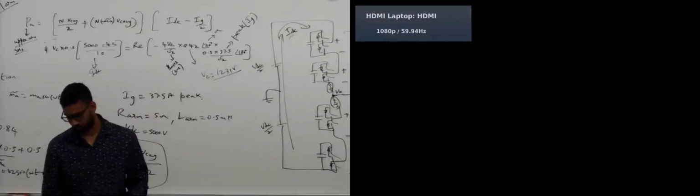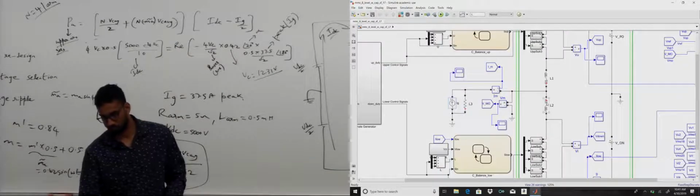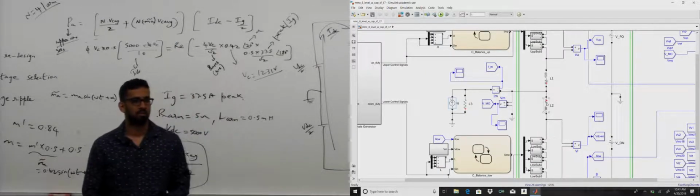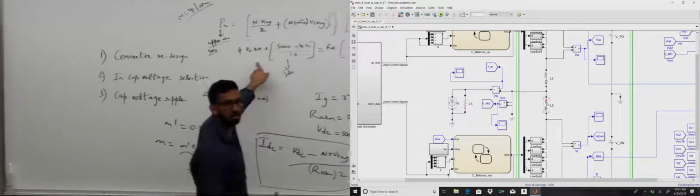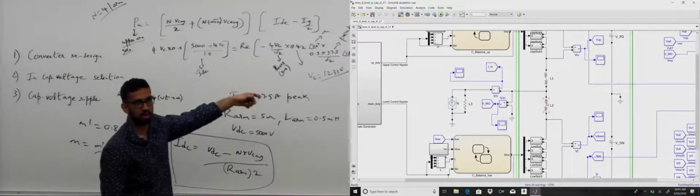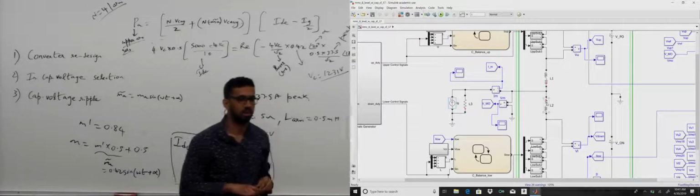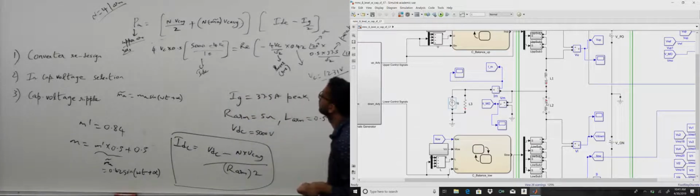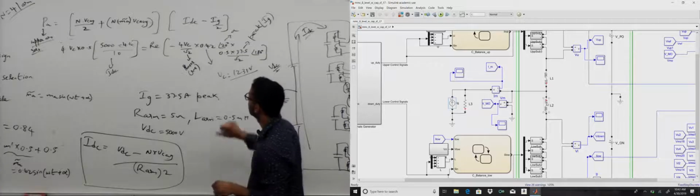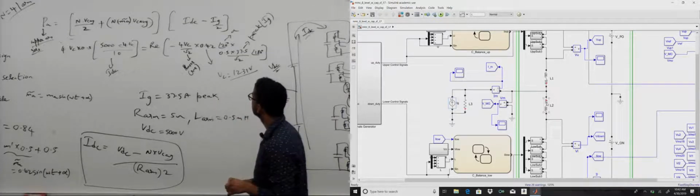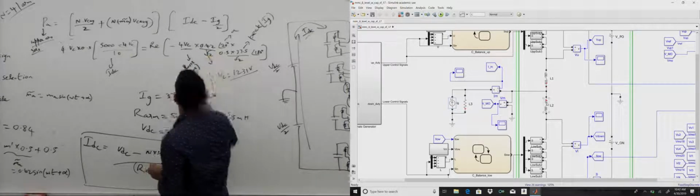Vishnu: For phasor representation, why is the one Vc average divided by root 2 and the other one is not divided by root 2? Here, this is not phasor. These are all DC quantities. Only AC quantities have phasor meaning, right? On the right side as well, n times Vc average term, only that ma term has your phasor, right? Yeah, so you can say by root 2 here.